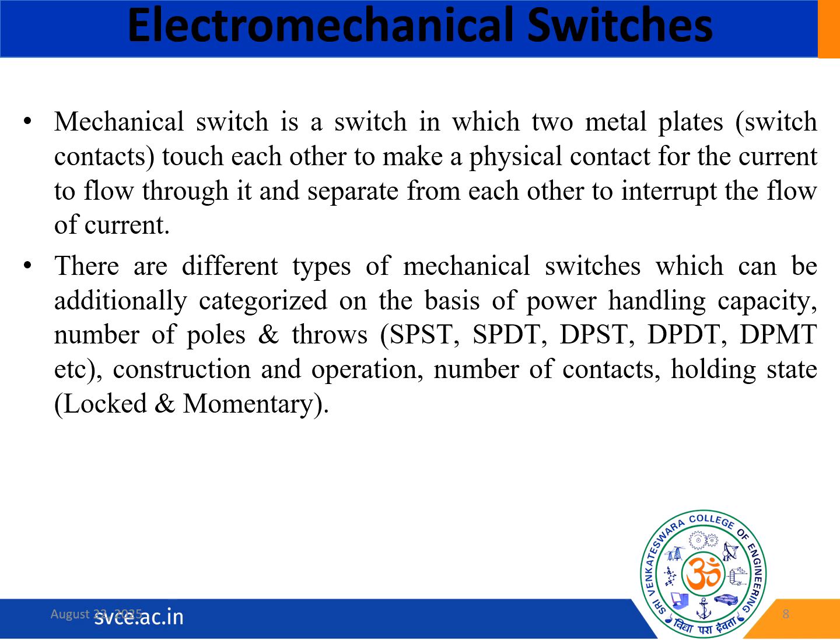So mechanical switches are highly versatile and can be classified based on several parameters. Considering the classification criteria, they can be classified based on power handling capacity, which determines the suitability for low voltage signaling or high power switching. Then poles and throws, which define the number of independent circuits and output paths. We are going to see the different types of switches here.